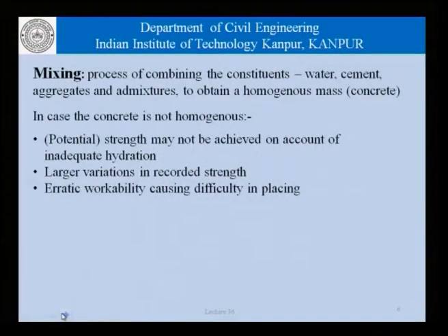So, improper mixing will affect the properties of fresh as well as hardened concrete, and we want to avoid that, so we must pay close attention to achieving a uniform homogeneous mass at the end of the mixing process.